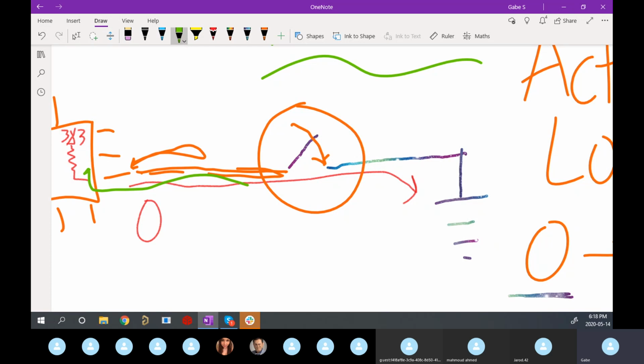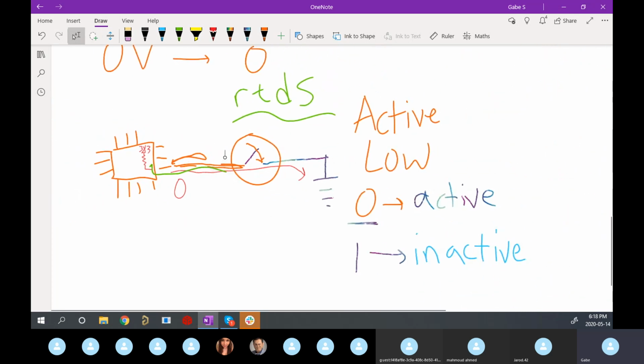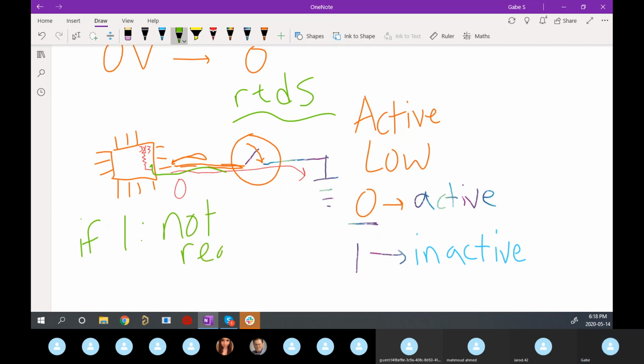And so whenever we untoggle the switch, or the switch isn't fully toggled yet, the driver's not ready yet, then that pin is pulled up to 3.3. And so we'll know safely that if we're reading a 3.3 on that pin, so if we see a logic 1, then we're not ready. Not ready, right?